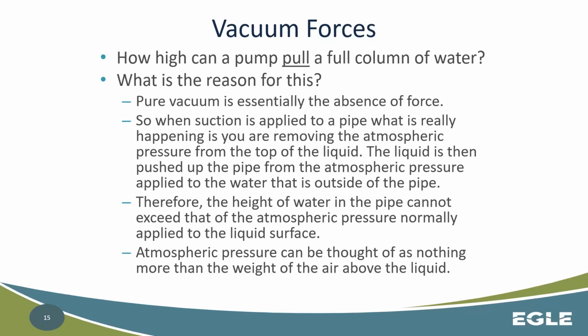So pure vacuum is essentially the absence of force. When suction is applied to a pipe, what is really happening is you are removing the atmospheric pressure from the top of that liquid that's in contact with the pipe, right? So the liquid is then pushed up the pipe by the atmospheric pressure applied to that water that is outside of the pipe. That's the pressure pushing force. And with the absence of pressure within the pipe, then that water will rise to a certain height, right?